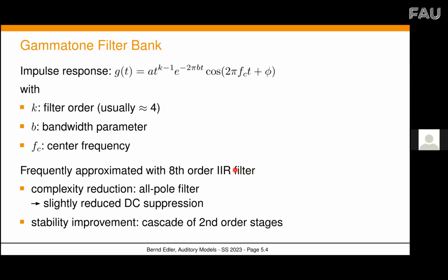And then from that, you can find in the literature, which I also will give you, and also in the examples I will show you. Then I will do that next time with some software. You can see how you could calculate the parameters of those IIR filters from the desired center frequencies and the desired bandwidth, let's say.